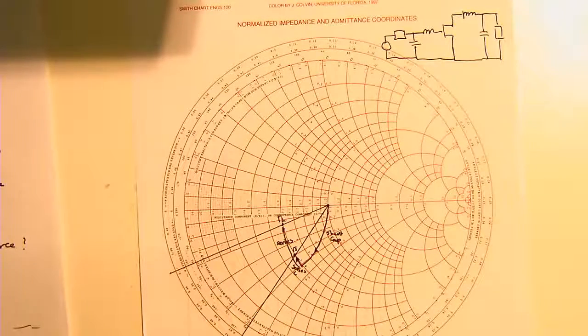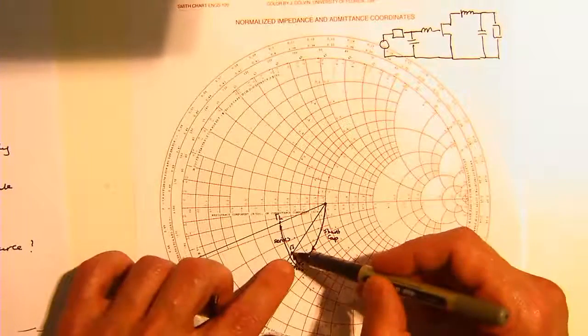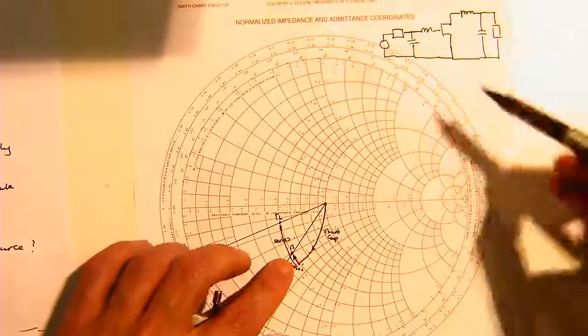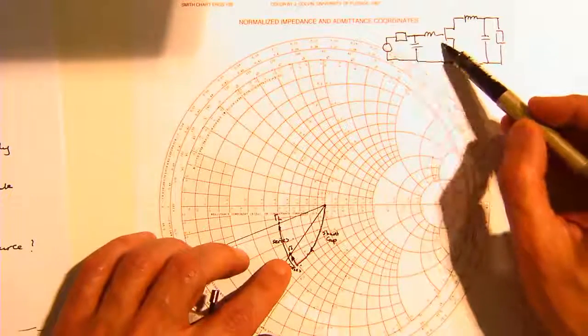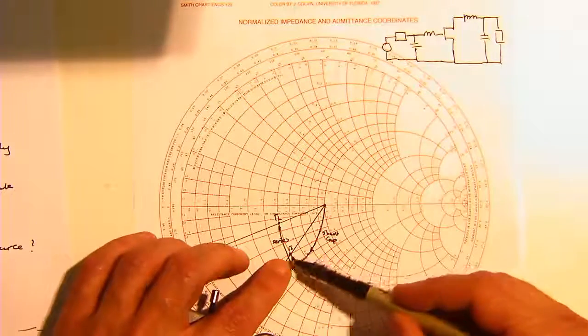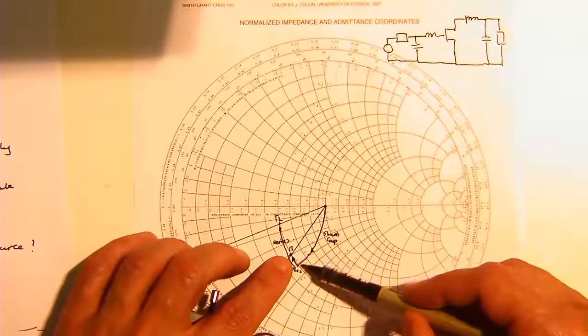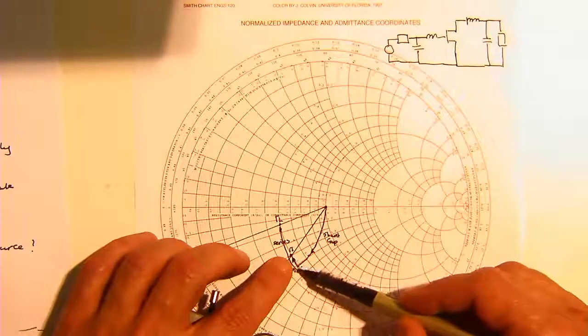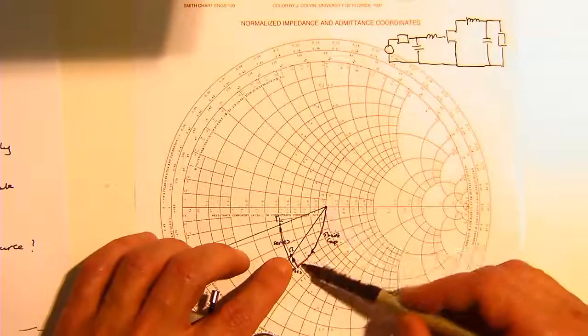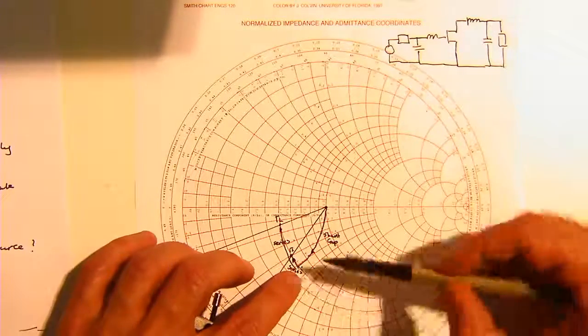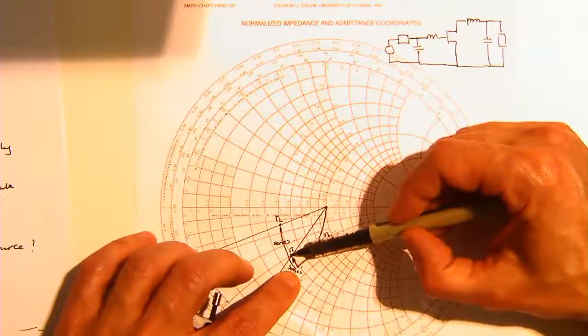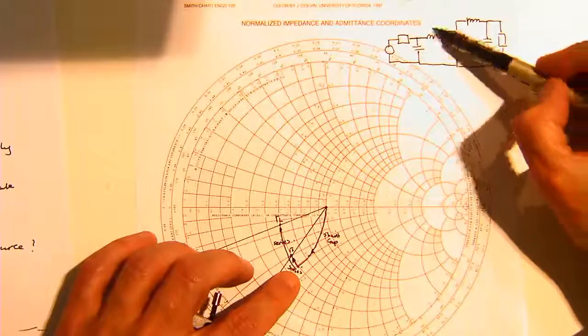We've discussed many times how to do that using our compass, and I won't go through it, but essentially all you do is draw your point gamma S. If you want to work out the matching network which transforms the 50 ohms to your desired value, we've got gamma S, we go down, in this particular case, the curve of shunt capacitance, so we know the value of our shunt capacitance. Then we'll add a little bit of inductance, and we get to the desired point. And we can actually work out what these values are.